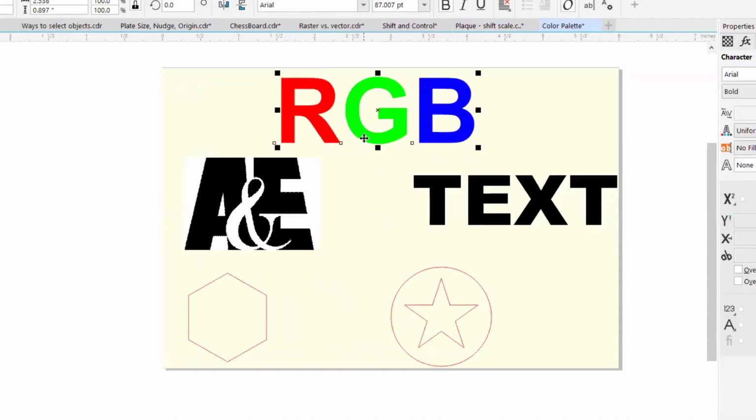Okay, so we talked about our default color palette that we really prefer is RGB, or red, green, blue. Now, Epilog laser systems prefer RGB, and the reason for that is that you can actually run CMYK, but what will happen is that CMYK black will not be engraved as solid black. RGB black will be engraved as solid black. Same thing goes for CMYK white. You would think that CMYK white would not engrave, but on many Epilog systems it actually will, and so you want RGB white. So again, let's talk about changing colors.